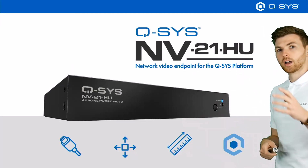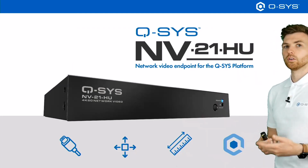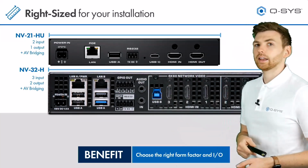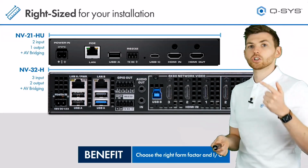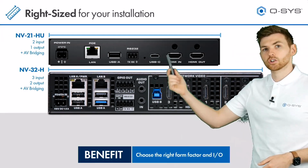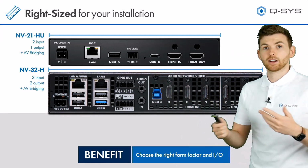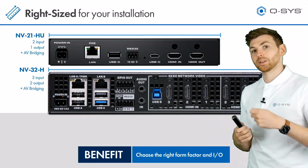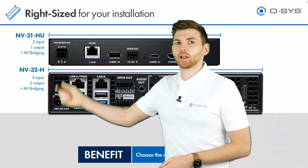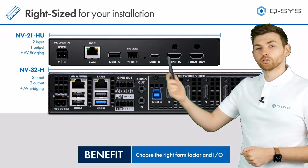And you see this is called NV21HU. That stands for HDMI and USB, as in USB-C. Because what people really want is the ability to connect a single USB-C connection and get device charging, USB bridging, and content output onto the network. And that's what this does. So that single connection is going to let you do all of the interactivity with the laptop that would normally take a USB and an HDMI. We just do it on the USB-C, and we're doing device charging if we have a power supply on this NV21.